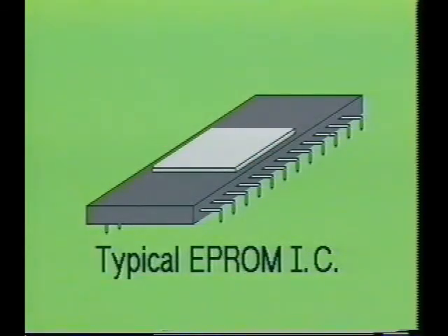After an EPROM has been programmed, it is recommended that you place an opaque material over the transparent window of the device. This is necessary because common sources of light, such as sunlight, room fluorescent lights, and blacklight, may contain enough ultraviolet energy to trigger random charge dissipation, which will introduce errors into the device.